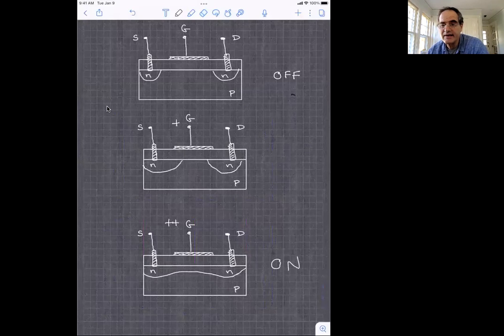Well, it's very much like the depletion mode FET that we talked about a moment ago. Only in this case, there were no electrons in the channel before we applied the positive gate voltage, but by applying a positive gate voltage, we pulled electrons into the channel. Okay? In fact, in some sense, there wasn't any channel before we applied the positive gate voltage. But this works just the same as the depletion zone device, and in much the same way. Okay, here, let's pause here.